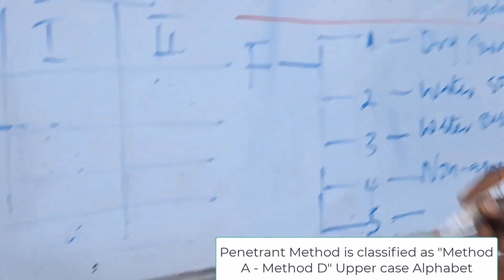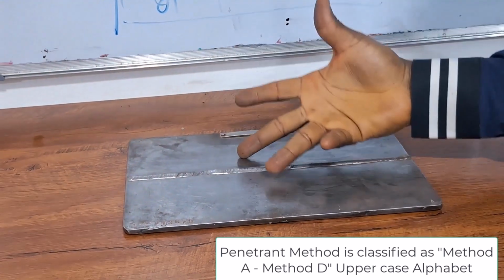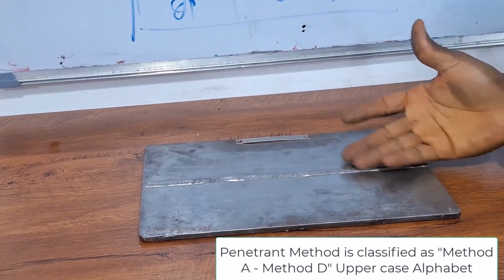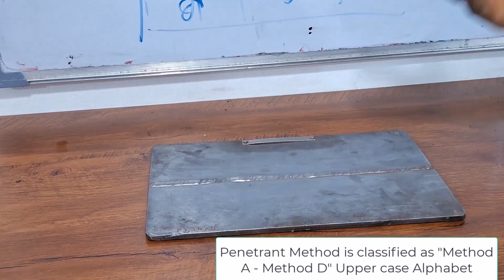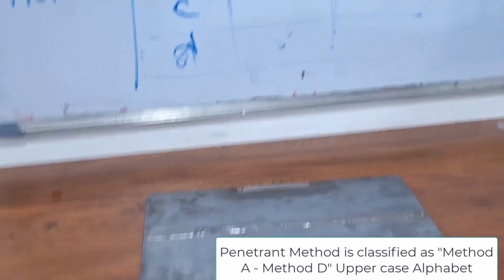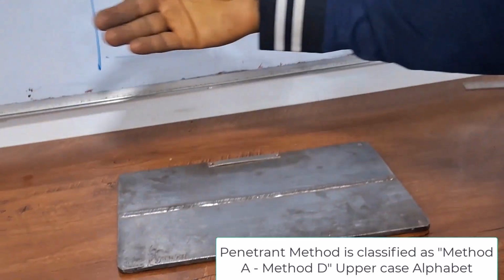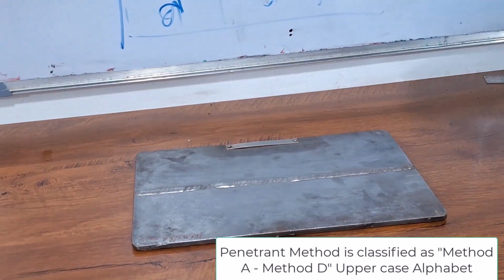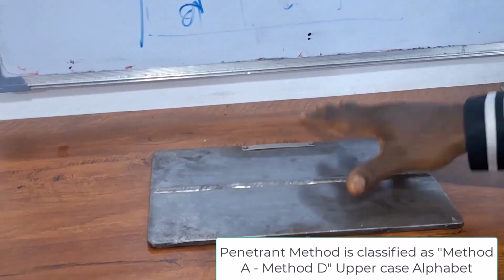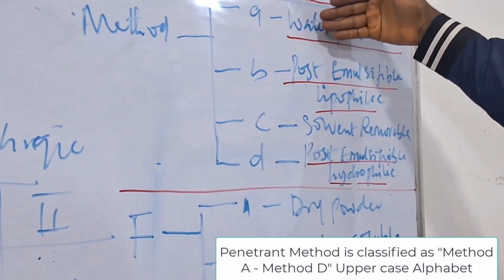Then you have the final one, which is the post-emulsifiable hydrophilic. It's still the same emulsifiable penetrant, which means you need an external emulsifier, an external chemical to make it water washable. But in this case, hydrophilic means water loving. Lipophilic means chemical loving. So in the case of hydrophilic, you apply your emulsifier, which is water based, then you use water to wash off the excess penetrant that has mixed with the emulsifier. That gives us the different methods.